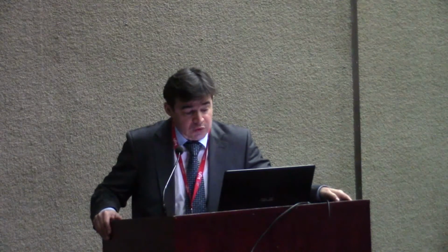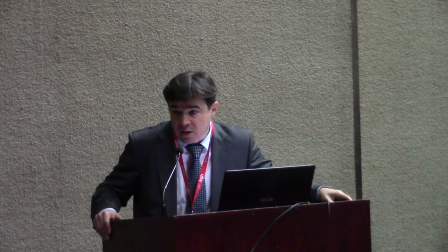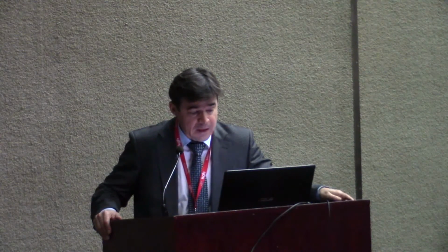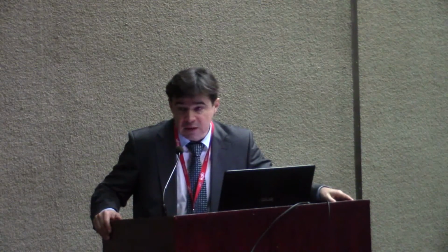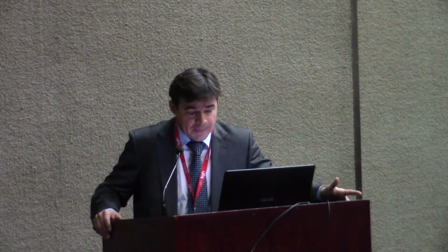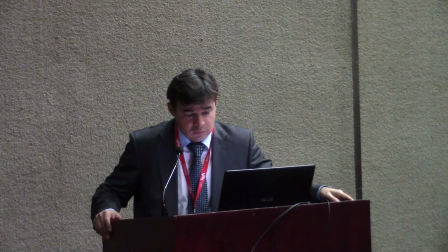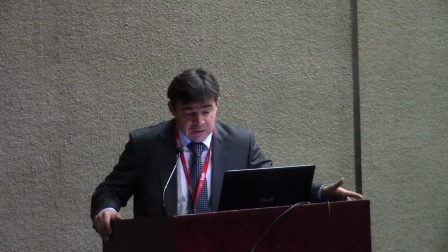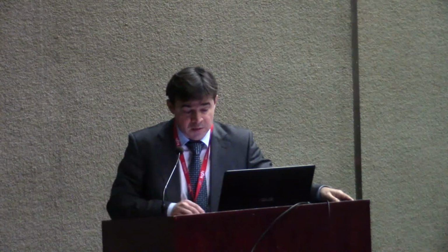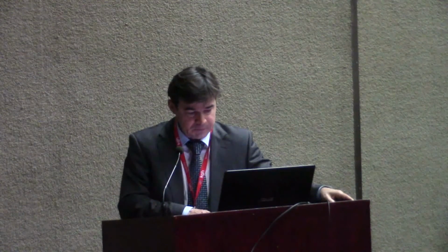Recommendations is to direct supply air in the lower zone of the space around perimeter, and air exhaust from space is better to organize from the upper zone. Air humidity in the space should be in range from 40 to 70%. Very low humidity increases energy consumption and negatively affects visitors' comfort.